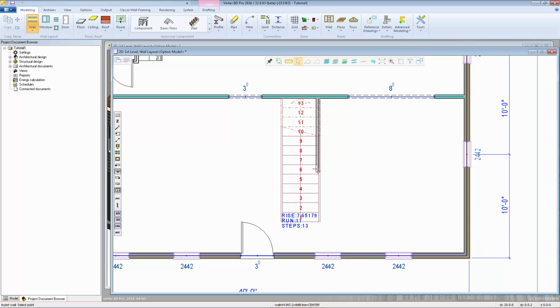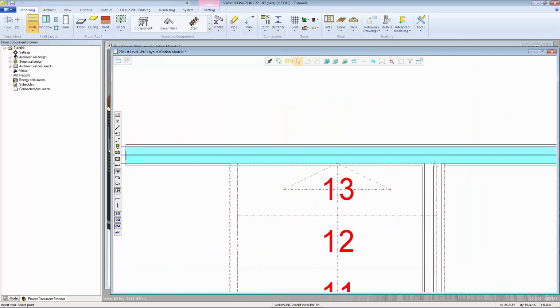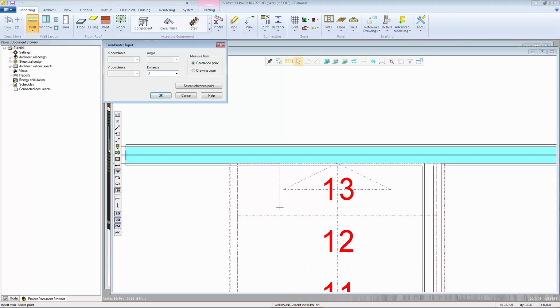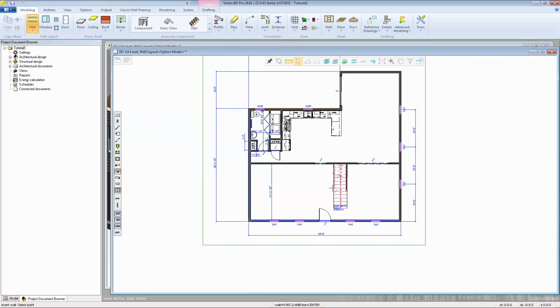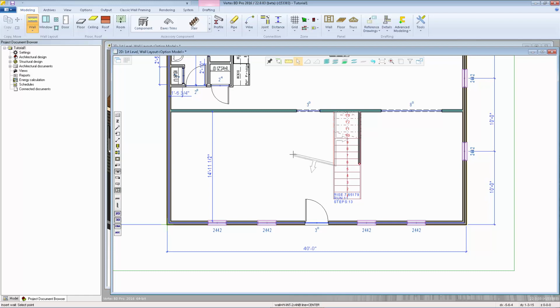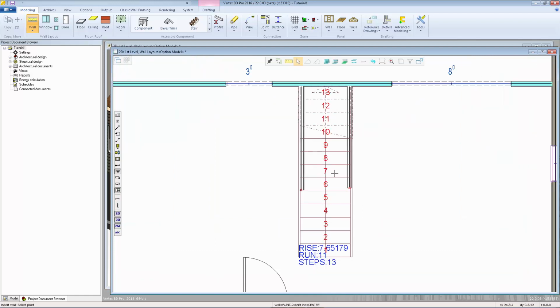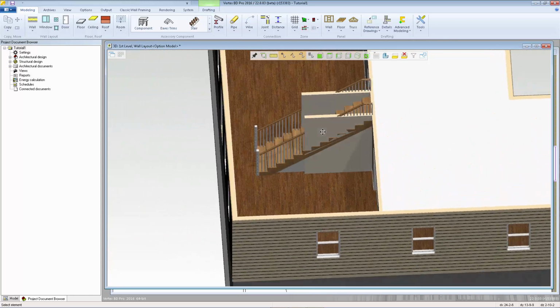We're going to use the wall shaping functions to get the right length of this wall. But first, we'll just add the other side. So I'm going to cue on the end of this wall, lock in horizontal. We're going to go across 3 foot and 3.5 inches. Lock in vertical again. And I'm just going to click around here and confirm. Then I can hit escape.